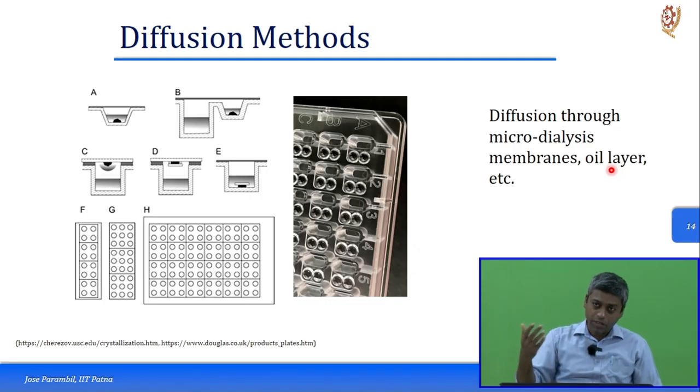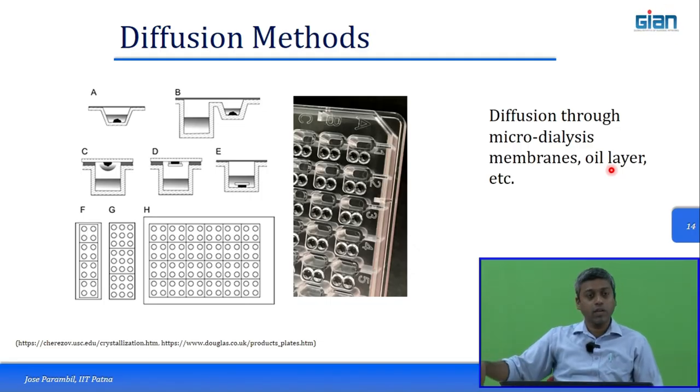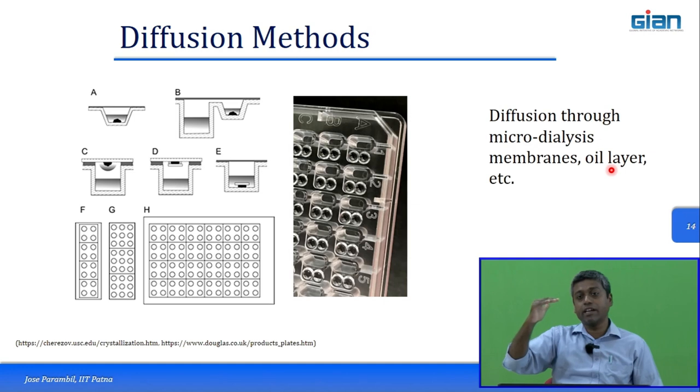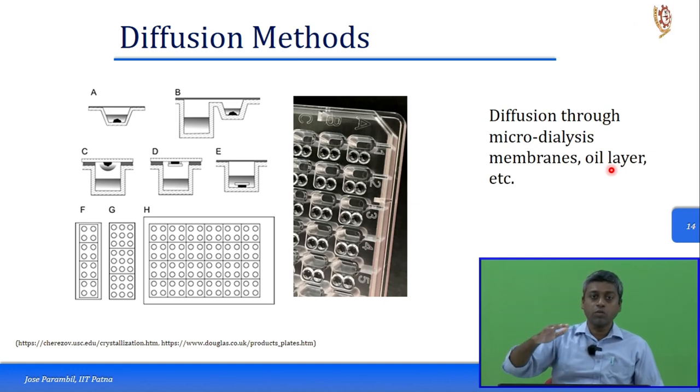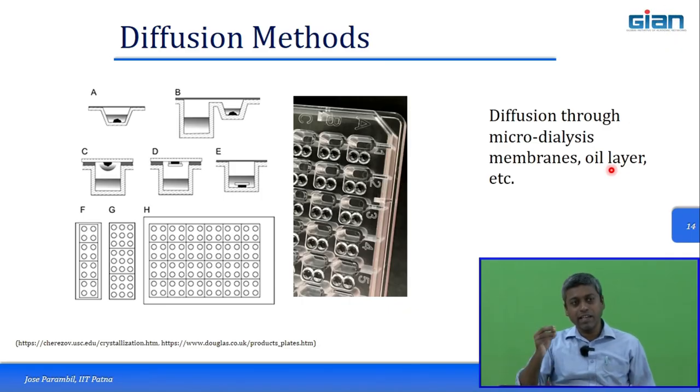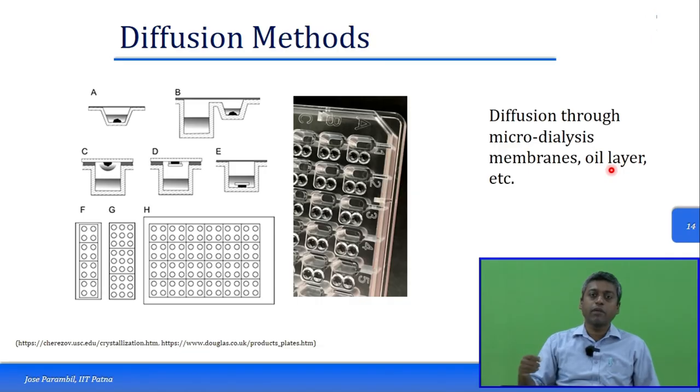If you have a droplet with, let's say, surfactants or oil on the top layer, that reduces the interfacial area available for the water molecules to evaporate. So it might arrest most of the evaporation. Of course, even though we say that oil and water are not miscible, a very small quantity of water might still dissolve into the oil and evaporate from the other surface, leading to a very small rate of evaporation.